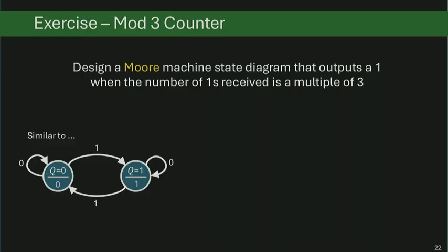So let's say with one state, one flip-flop, you can represent two states, 0 and 1. If you need 3 states, you need 2 flip-flops, which means every state is represented by 2 bits of information, right? The joint output from the 2 flip-flops.